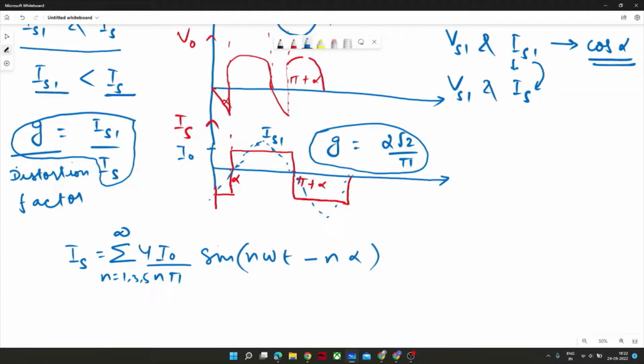So why am I writing this expression? If there is any square waveform, I am just telling you a shortcut. You can either derive it from the concept of Fourier series. But in power electronics, I believe that if you know the Fourier series of one or two kinds of waveform, you will easily get through all types of problems because you will majorly see a square wave. The work of power electronics is to provide a sinusoidal thing, but it fails in that purpose, so it tends to provide us a square waveform. So anywhere you can see that.